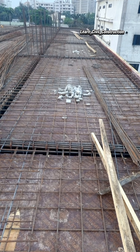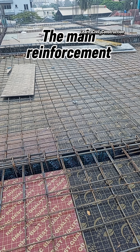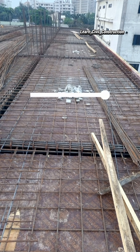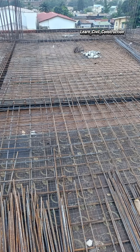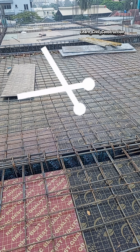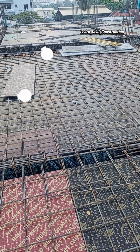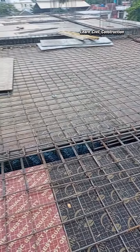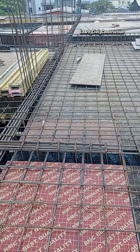So the reinforcement for a one-way span, the major reinforcement, that is the main reinforcement, is always across the bottom part. Then you can distribute it with a distribution bar, but the bottom one is the major reinforcement. But for a two-way slab, it means you have 2 main reinforcements. That's the 2 reinforcements at the bottom. They are the 2 major reinforcements. It is distributing all of its load to all the beams around.